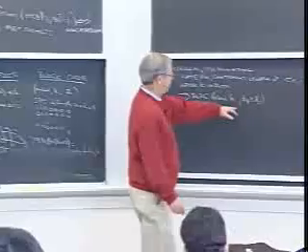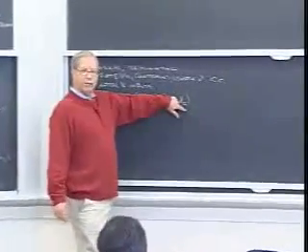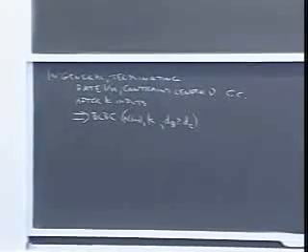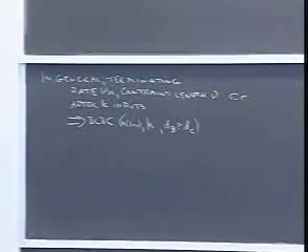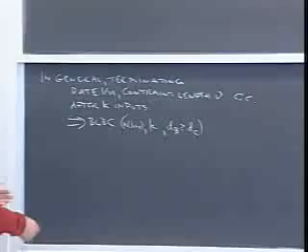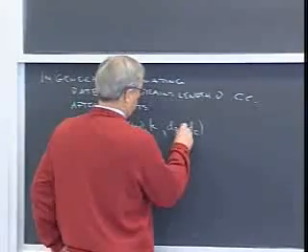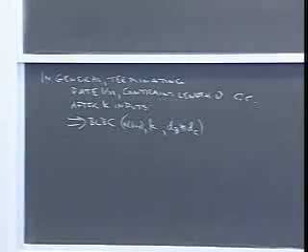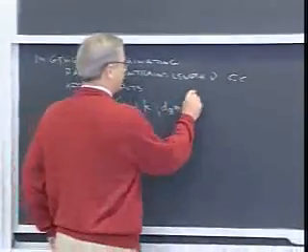I'm assuming here that the code is not catastrophic, so that it's sufficient to look at all the finite sequences in the convolutional code. All right, and in general, the block code distance is almost always going to be equal to the convolutional code distance. And this is just for finite code words.